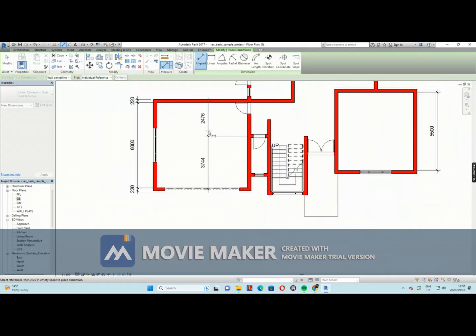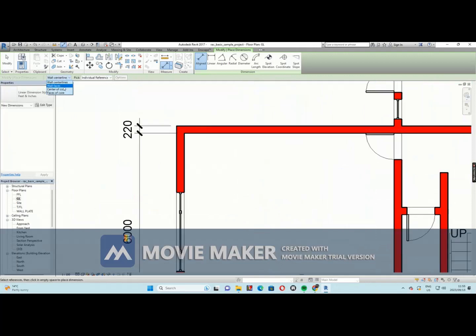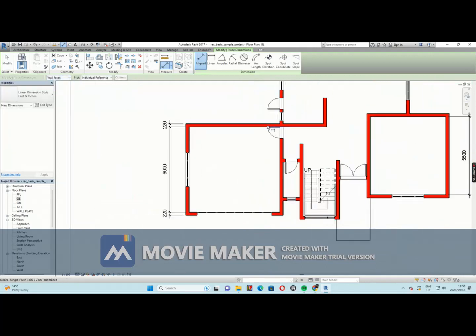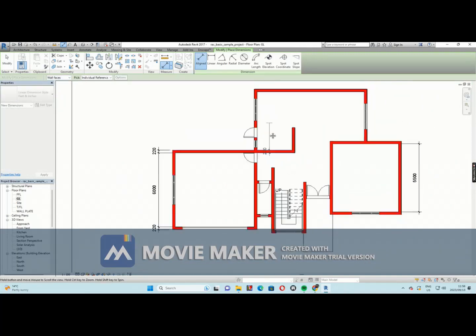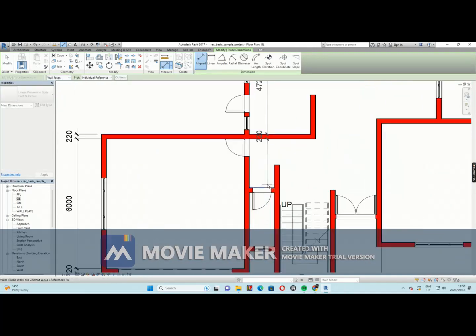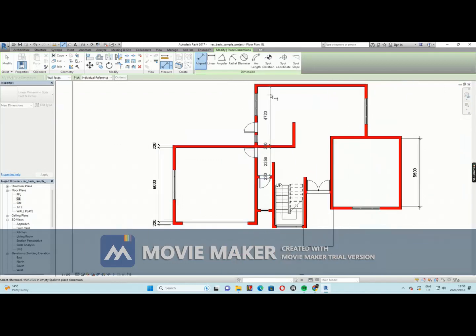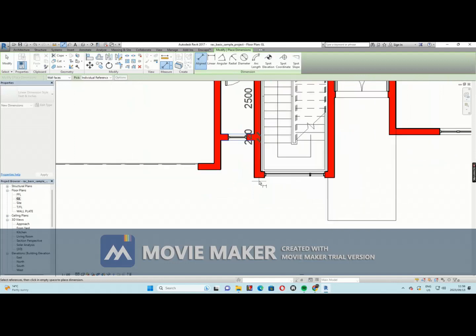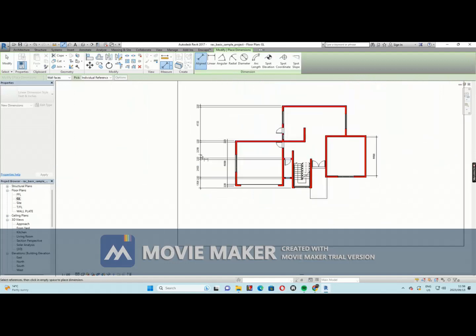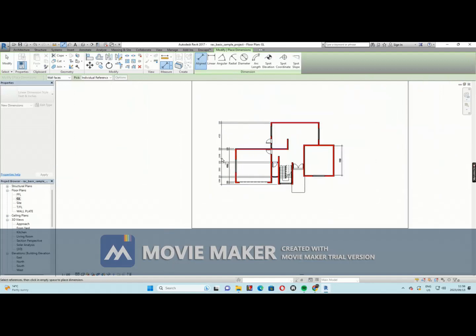Revit doesn't care if you miss a wall. Let's say you are going this way, then you can suddenly change your direction to come this way. Then you can also come and finish up with, then you can also come this side. It doesn't matter. As long as you are clicking your dimensions and you have your dimensions, you put them somewhere. Okay? The dimensions for the meantime.